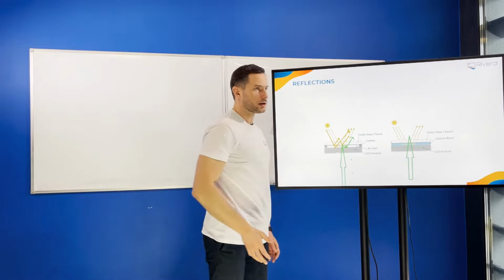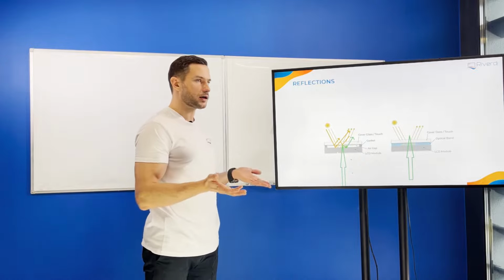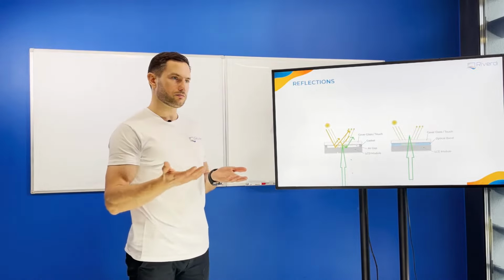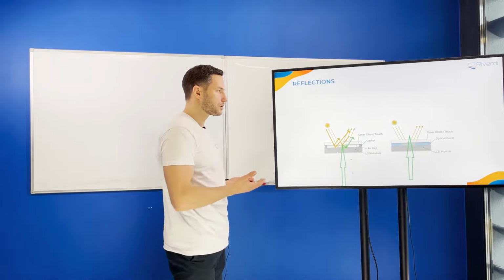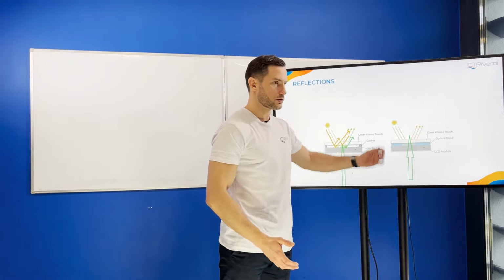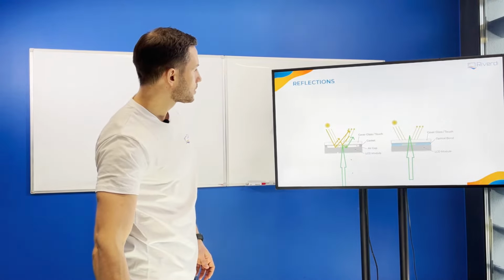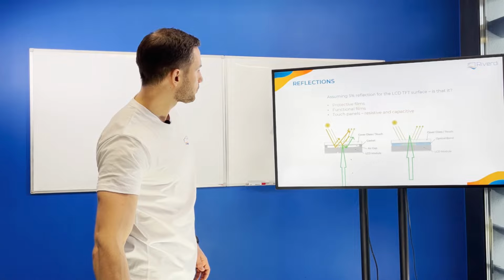This image is way clearer. If you had a chance to compare an air bonded display and an optically bonded display, you will see that the colors are better, more vivid. The image is literally clearer in this situation. It's because the whole light is just going out, yes, without any reflections, scattering, or anything like that.